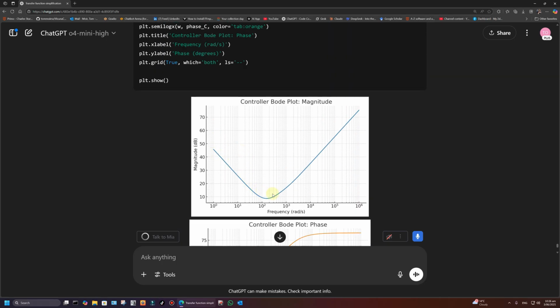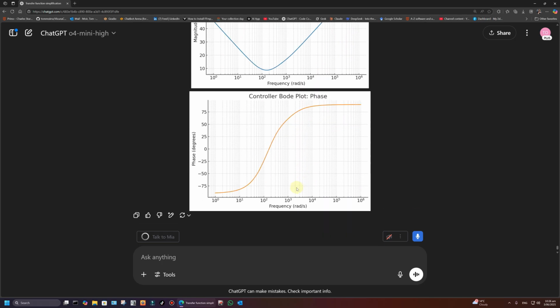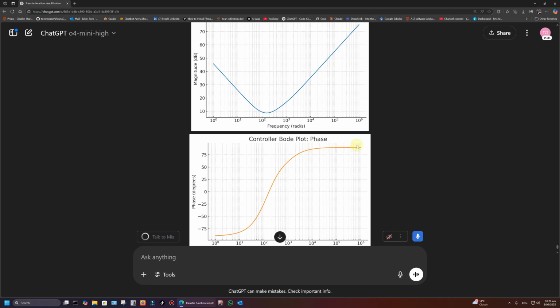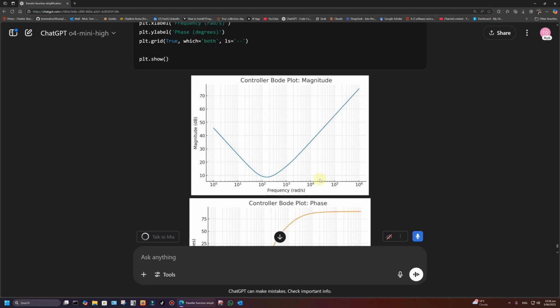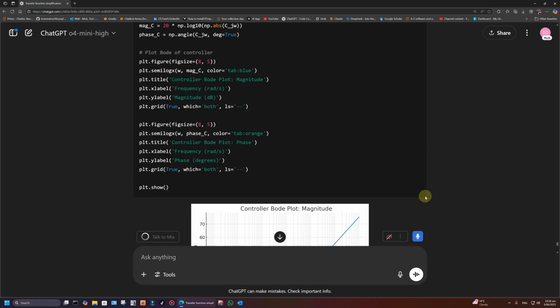So it's an integrator and then this lead term. The phase closes off there. That's brought down later by the minus 40. Actually, it's a second order resonance, so it's minus 40 dB per decade roll off on the original.